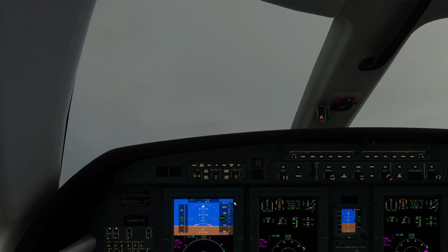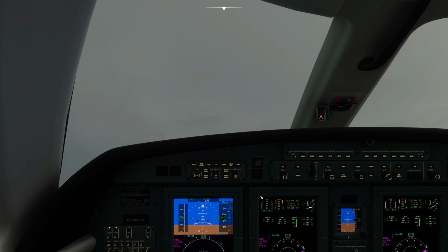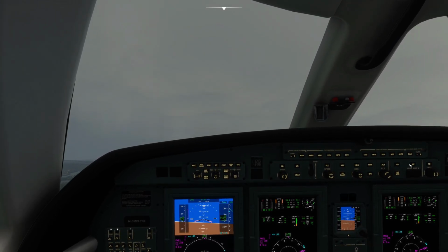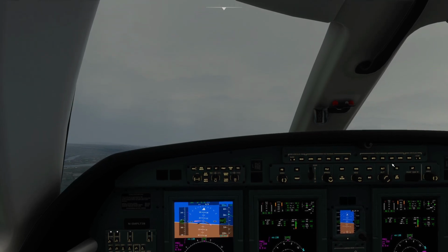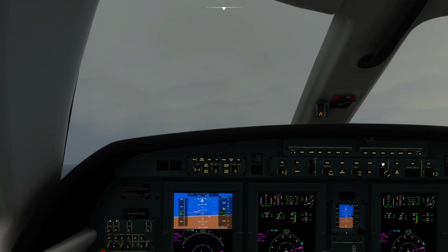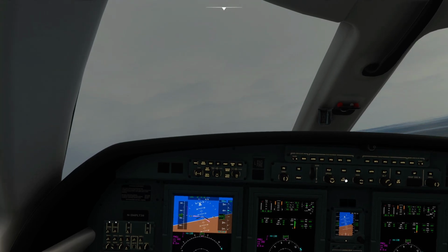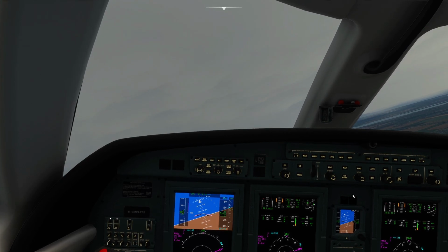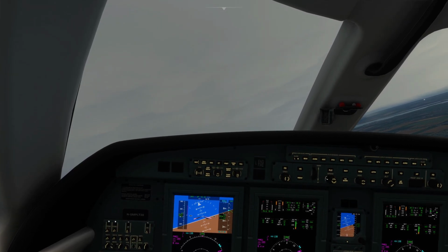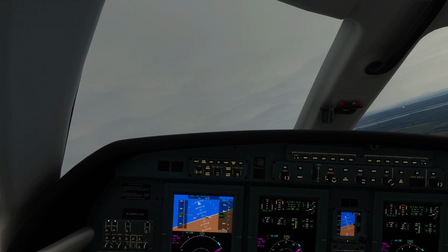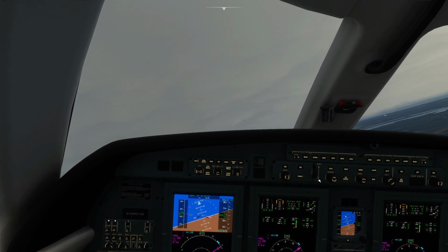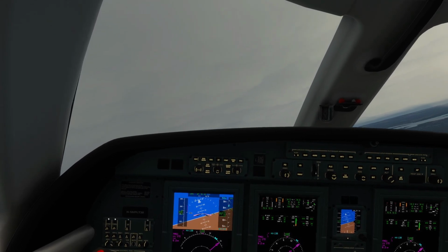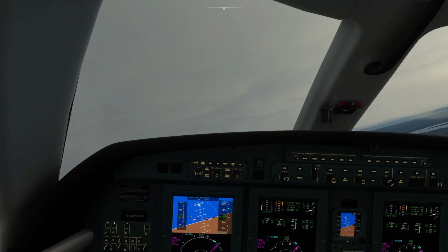Air Canada 1350 Alpha Charlie Alpha, contact Vancouver departure on 132.0. Okay, so now the yaw damper and autopilot can come on, and we can leave it to the autopilot, and we can do half bank so as not to upset the passengers. Oops, slow down. You don't want to pass 250. Yep. We are going to increase the climb speed slowly.